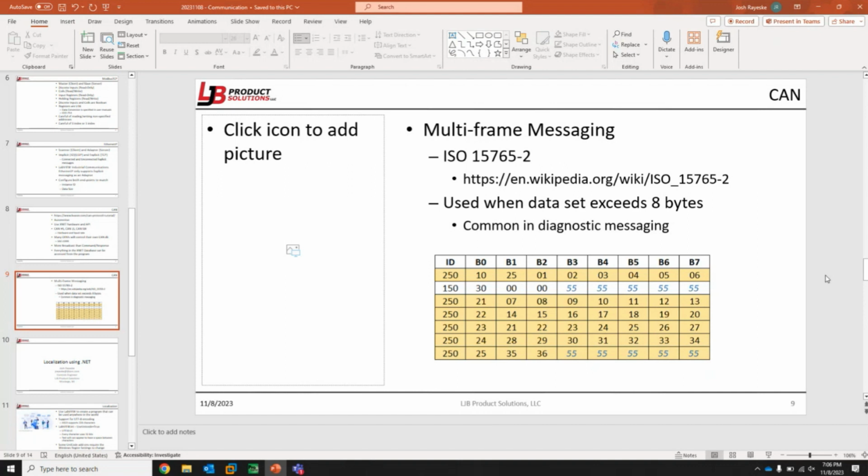Modbus, I don't think it really cares if it loses it or not. So there's no bit that says I have no Modbus connection. But having some revolving value going between the two will at least let you know that the connection's live. Yeah, but being able to expose all of those data elements at once would be nice without having to create a data socket or something for every one of them.